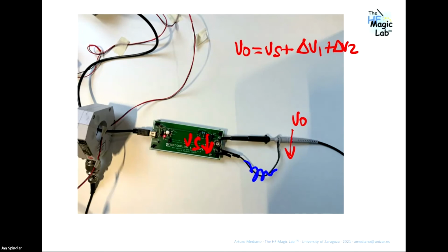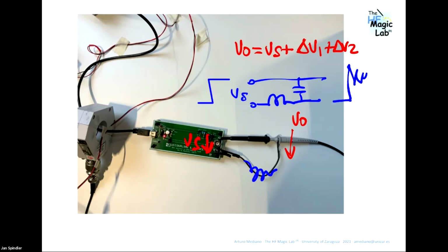So what happens? This is your signal, VS. This is the inductance of the pigtail, and this is the input capacitance of the probe. So what do you have? You have an underdamped system. So when you have a square wave signal, the output of this element is ringing. So the ringing is not from my signal, it's from the setup.